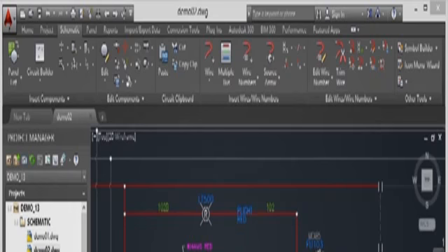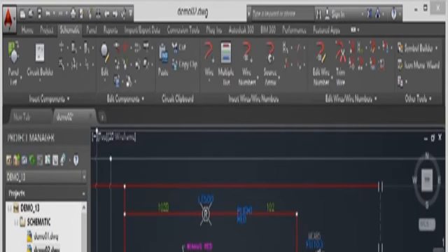However, you can also select the component you want to copy, like so, right-click, and on the right-hand menu, you get the option there to copy the component. So if I click there on Copy Component, come away here, go further along the wire length and click there. Because it's a new component and I'm copying it, it automatically updates the component tag. So I've now got an LT105B and I can edit that to whatever component tag I want it to be. Click on OK like so, and you can see now I've got LT105A, LT105B.